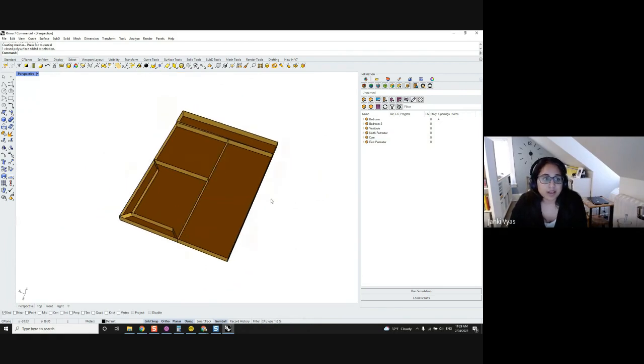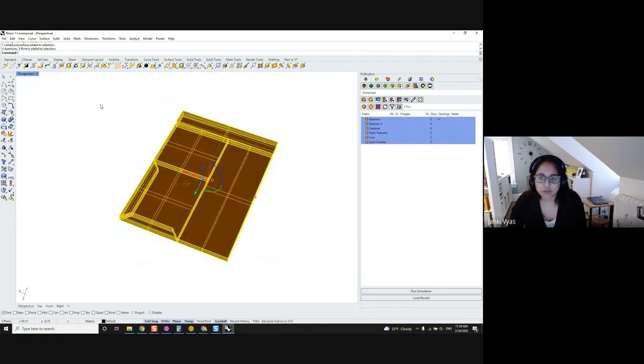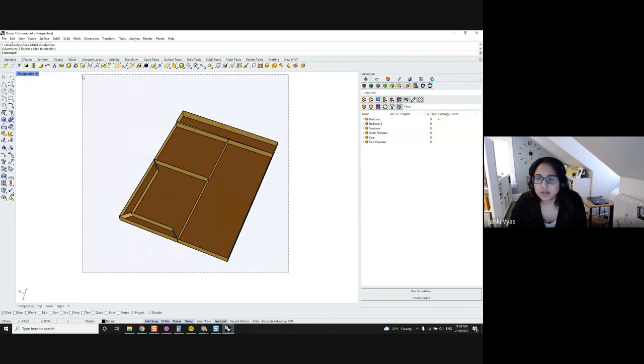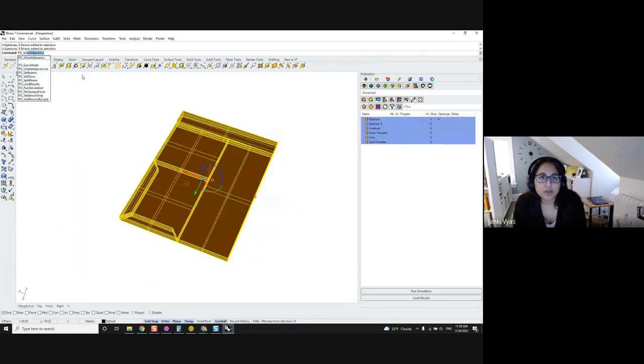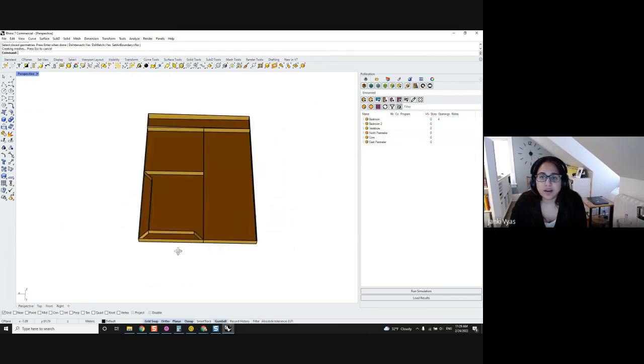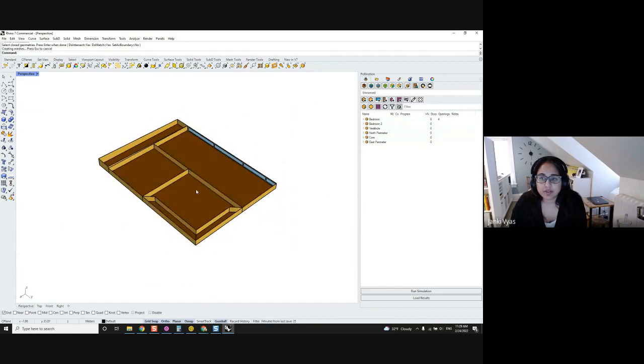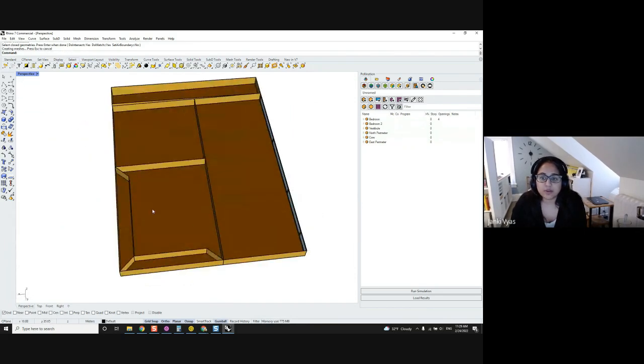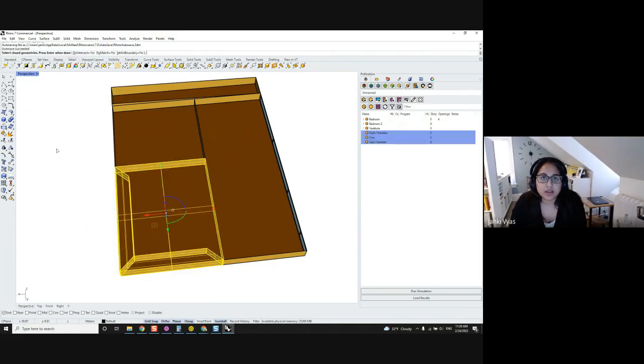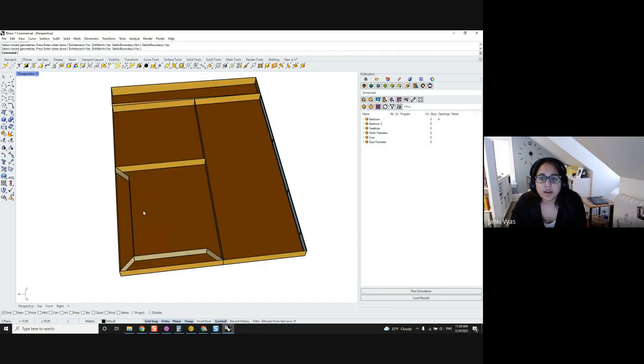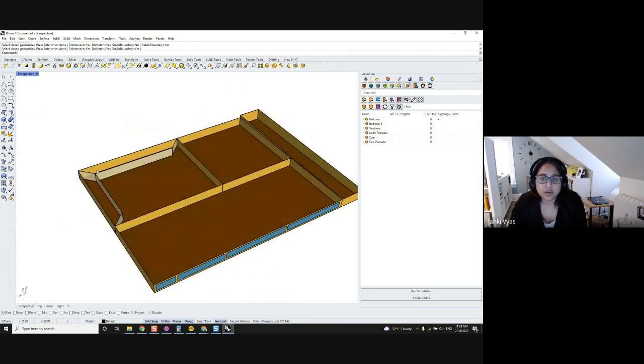So before we go back and add our windows again, I'm going to actually hit solve adjacency. So type in PO solve adjacency, and that takes care of intersect and matching. And for now, I'm not going to set air boundaries. And then you can see that it converts everything to interior rooms, but I do want some air boundaries in this space. So I can select this and hit PO solve adjacency again and say set air boundaries only on the interior walls in this space. And that will change the boundary condition there.